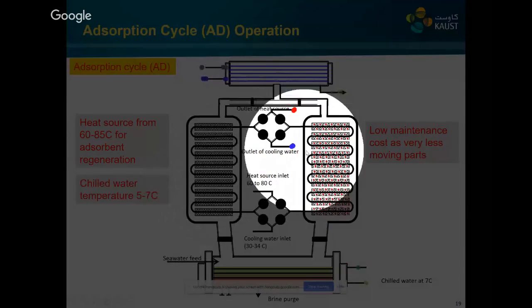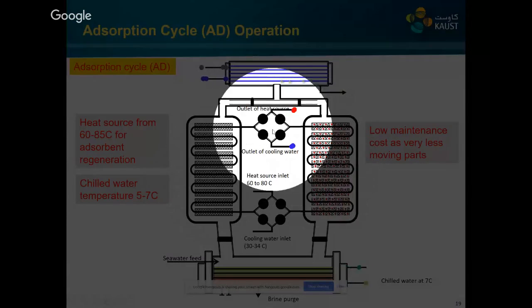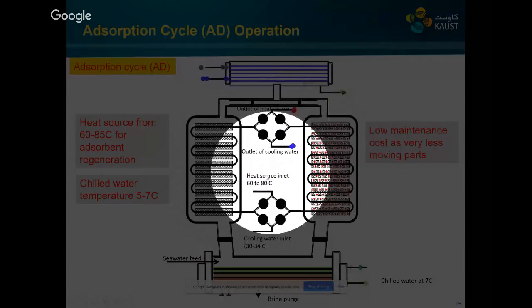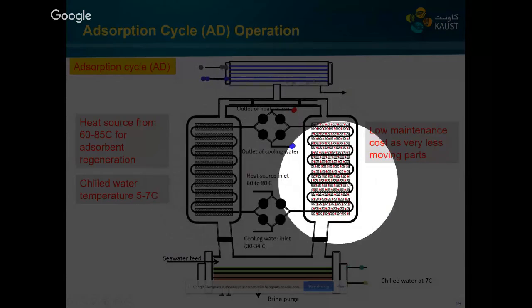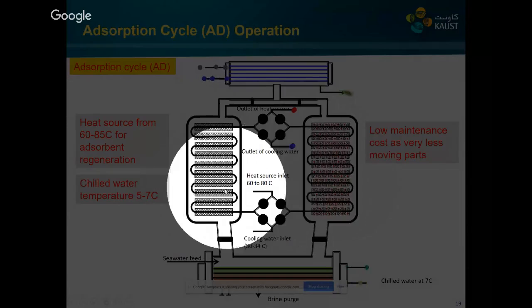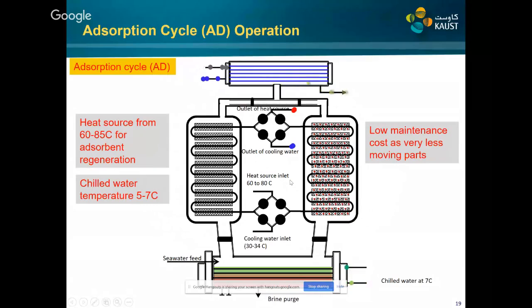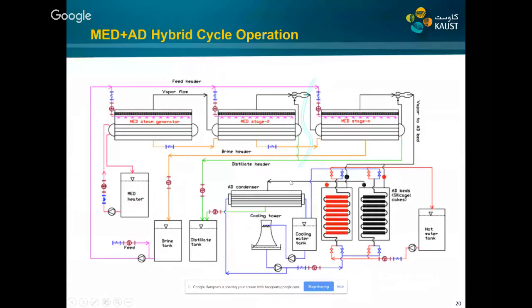So its system requires very little maintenance, except only the valves that are actually opening and closing. And the silica gel is also stationary, and this is a physisorption process, not a chemisorption. So it's a very stable and very reliable system. So this is how we integrated.